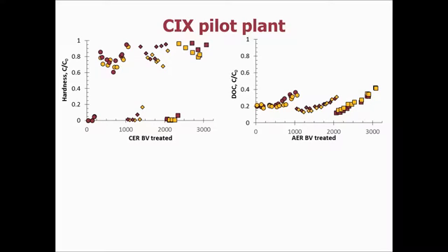And so that data is consistently showing that over the 3 cycles. And when we look at the regeneration samples we collect and try to do a mass balance on the regeneration efficiency of the process, we're seeing that we are desorbing the majority of the calcium that goes onto the resin, and so we are getting effective regeneration, and that's shown here in these results where we get this repeat performance for each cycle.